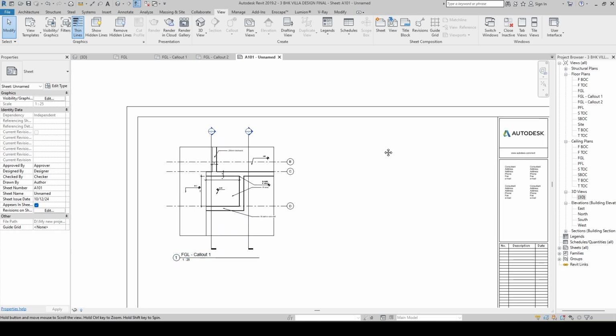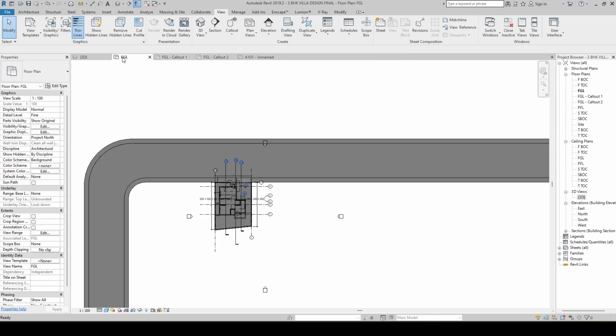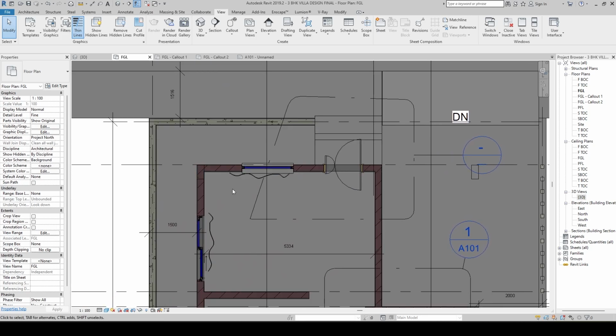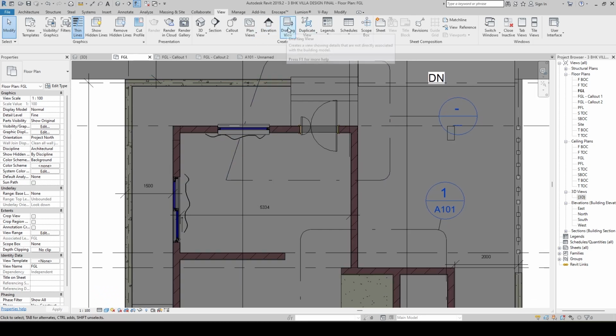And then one more, you have the feature called the drafting view. Drafting view, in the sense, this feature is useful when the typical details are not particularly applicable to one particular area. It's going to be typical. That means, say for example, you are having the first floor somewhere here, you are showcasing the window details here. On either side, the finishing details are unique for all the buildings, I mean throughout the building. Those kinds of details you can just showcase as a drafting view.